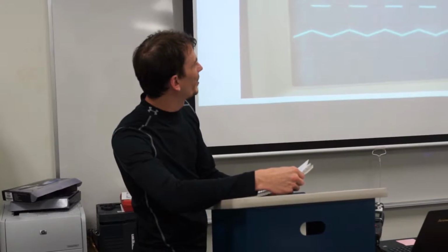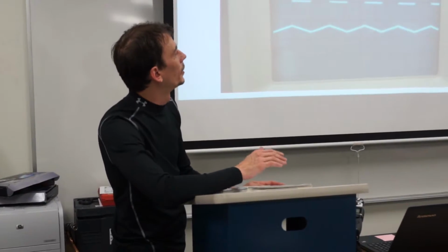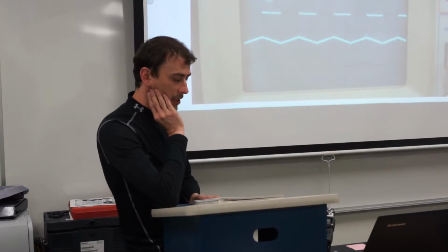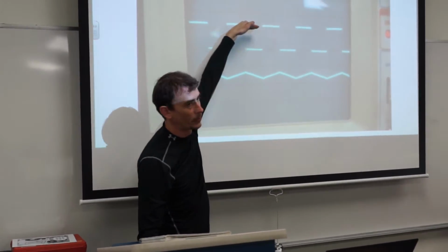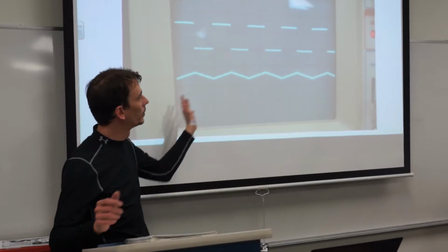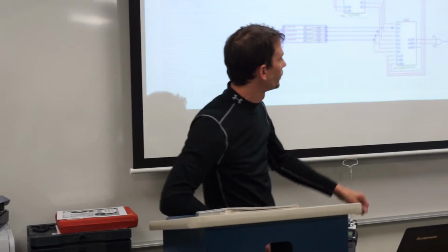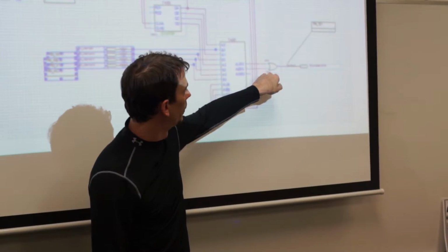Another challenge, which is probably extremely picky and in the application of this particular device is completely useless, but just using the higher than output from the comparator, I realized it wouldn't be possible to get a technically true 100% full on output from the comparators, giving what you could call actual full output from the whole system. With these comparators, I thought it was handy because it had the 3 outputs. So by tying in essentially with an OR, I think if you go back to this one, so back over here, I just OR'd the A less than B output with the equals output.